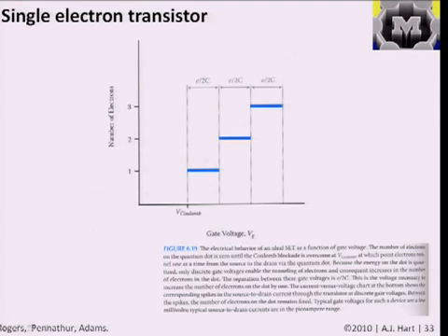And for example, the dimensions of the device and the voltage difference between the source and drain electrodes will also determine the current. So for example, it can be determined by characterizing this device how many electrons you have on the dot at a time, and also what the current flowing through is, because you may not know if you have a certain current going through if that means you have 1 electron going through it at a time at, say, rate x, or 2 electrons at a time going through at rate x over 2. But characterizing this can let you figure that out.